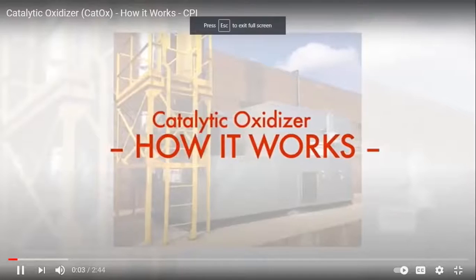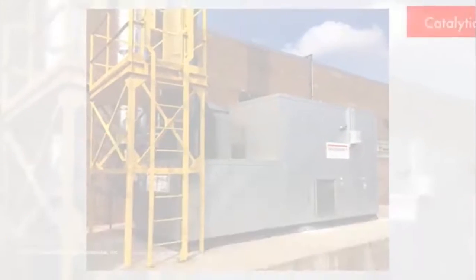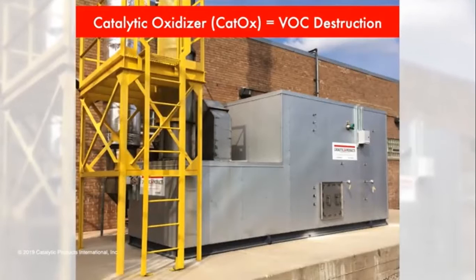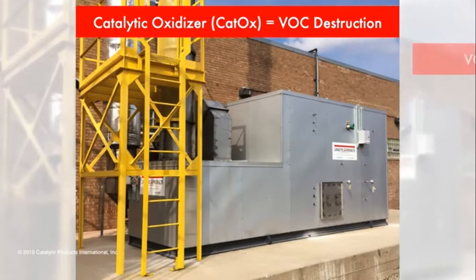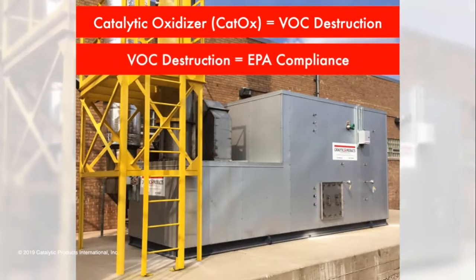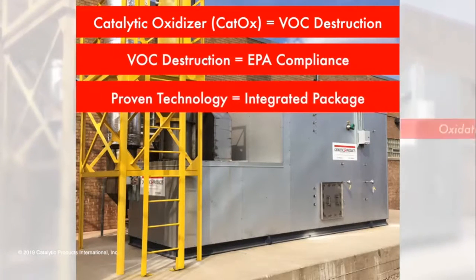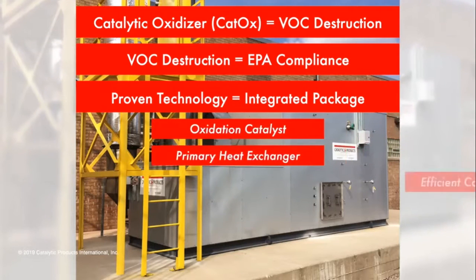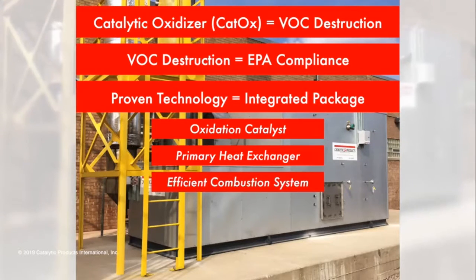Catalytic oxidizers are used across a broad range of industrial processes to efficiently destroy volatile organic compounds, VOCs, hazardous air pollutants, and other odorous emissions while enabling manufacturers to maintain EPA compliance. This proven technology combines a low-temperature oxidation catalyst, primary heat exchanger, and an efficient combustion system into an integrated package delivering cost-effective destruction of VOCs.